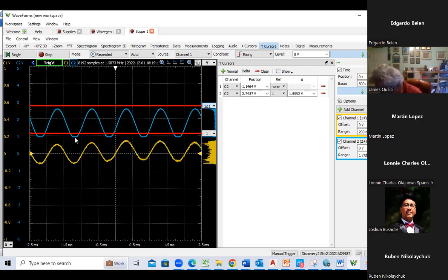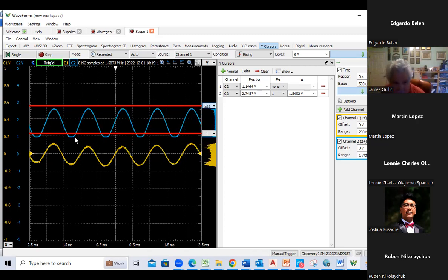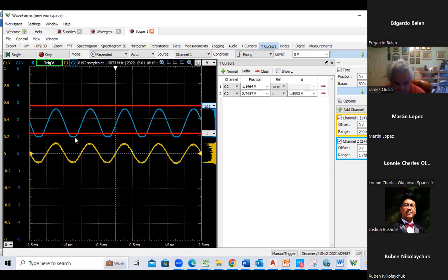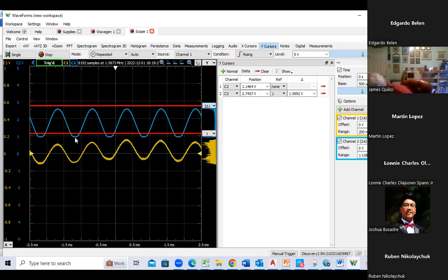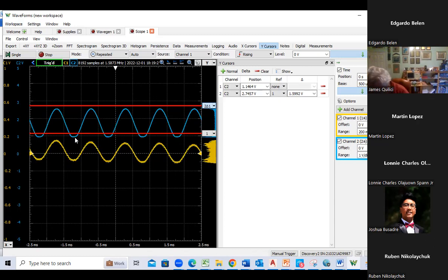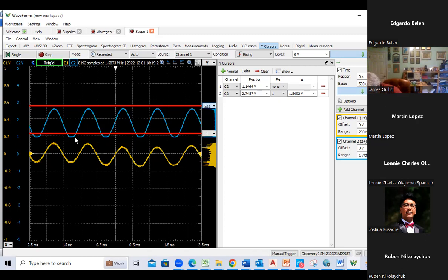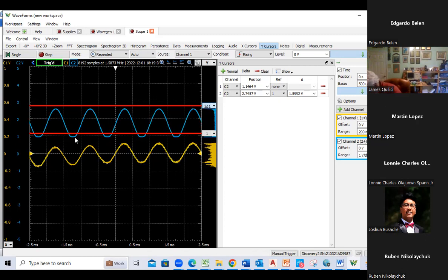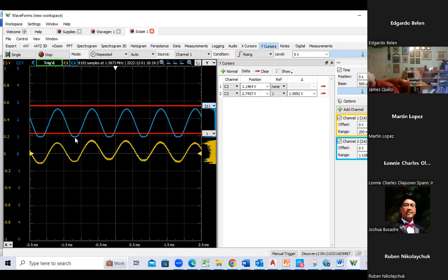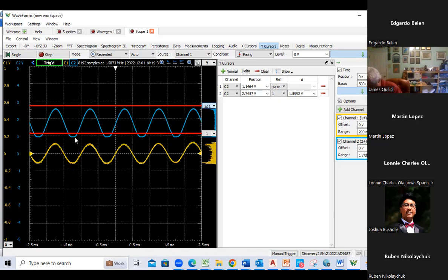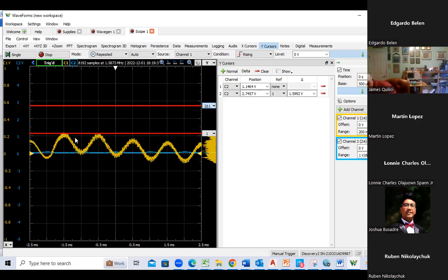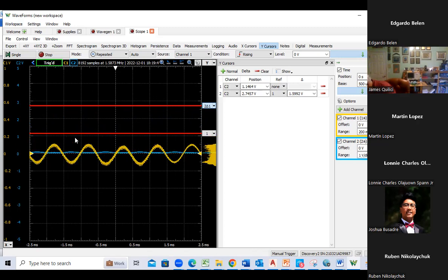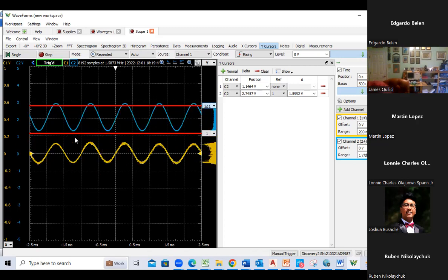I'm going to put 2K back there. Yeah, I'm going to put 2K back in there. And then I think I'm just going to reduce my emitter resistor again and see if I can get a little more gain out of it. My gain was 10, and so it's got a spec of plus or minus 10 on it too. So I want to get at least 9.